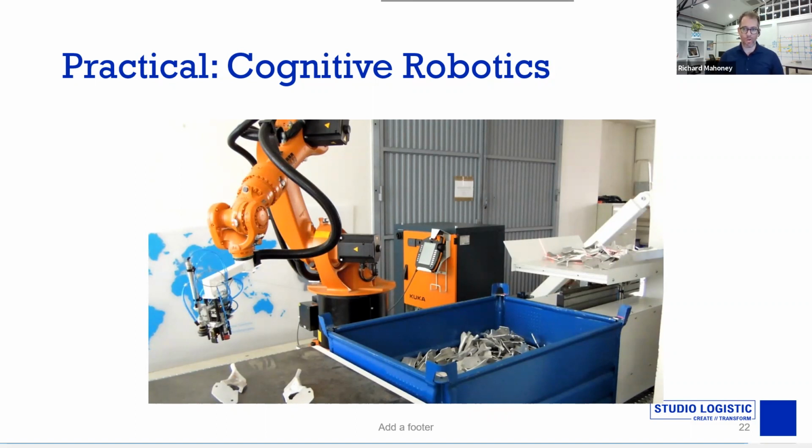And there are now one or two examples in Australia where goods to robot picking systems handle loose stack bin random odd shaped parts. The example I'm thinking of is Sigma Pharmaceuticals in Sydney that went live, I think earlier this year, and has a system that works like this, where you present the tote to the robot, and the robot picks from that, and it just sequences that out.